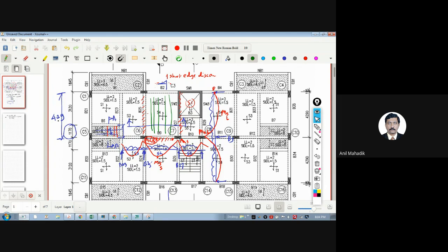which I am designing for this vertical steel you can see at the bottom. So this is my bottom steel. Now there is MHL. So I need to put the steel on the beam B9 also, over the support. Over the support, I will put the steel like this. Okay. So this will be your over the support, correct? Which is for this bending moment. All of you getting this? Yes, sir.